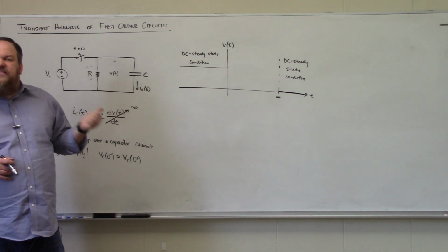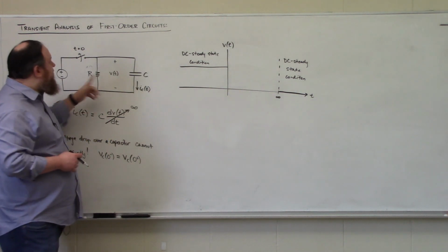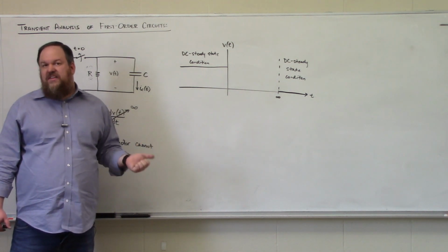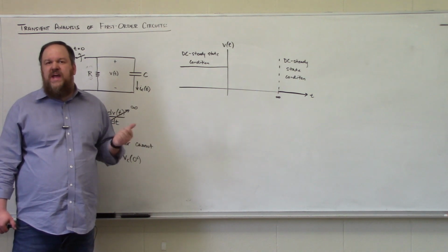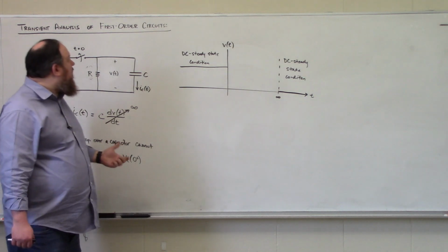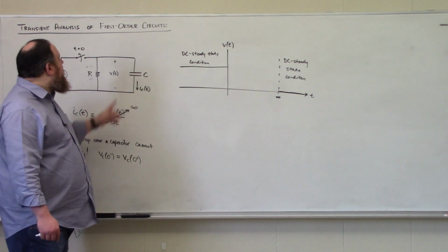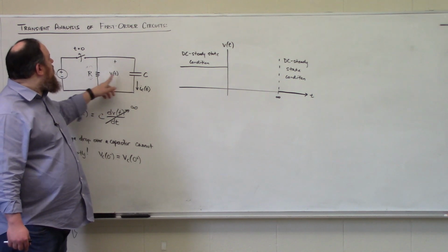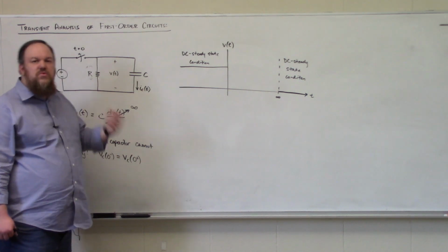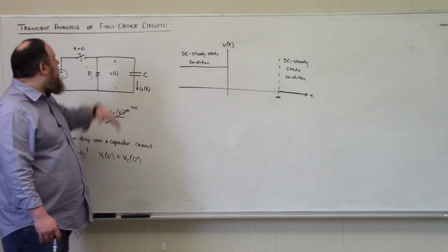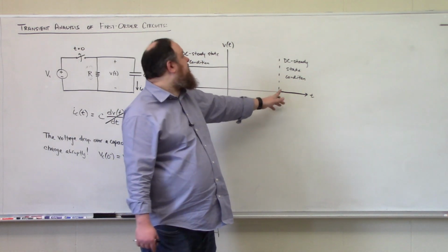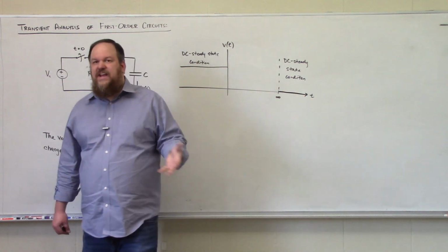So what I am trying to explain is, let's talk about the instant that t is equal to 0 minus, okay? There was a voltage drop over the capacitor, which means that there was energy stored by the capacitor. Since the energy stored by a capacitor is 1/2 CV squared, if V is non-zero, the energy is non-zero. Over some amount of time, the energy stored by this capacitor will be distributed to this resistor and transformed into heat. So we're never losing energy, we're effectively just bleeding it off as heat until such a time occurs that the voltage drop over the capacitor decays to 0 and we are at steady state again.